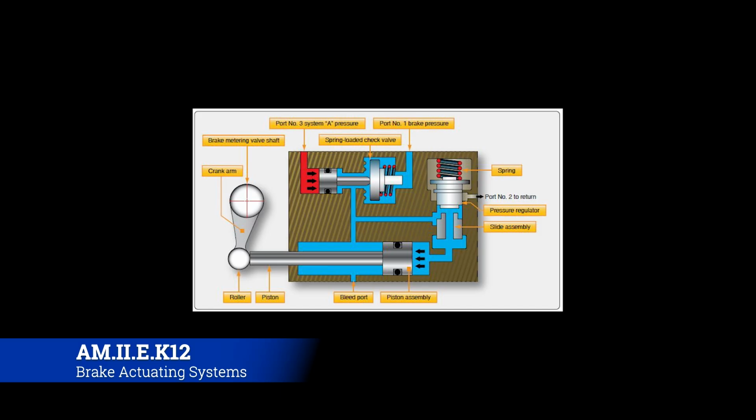Now, once we're through the brake check valve, we get to the accumulator. Remember, an accumulator allows for instantaneous hydraulic pressure to be available whenever needed, and it also helps to develop hydraulic pressure and recover it much more quickly than a pump will. There are still pumps that move the fluid, but the brake accumulator uses bleed air to help pressurize it to a high degree. The blue on there represents the air side. The red is the actual hydraulic fluid side.